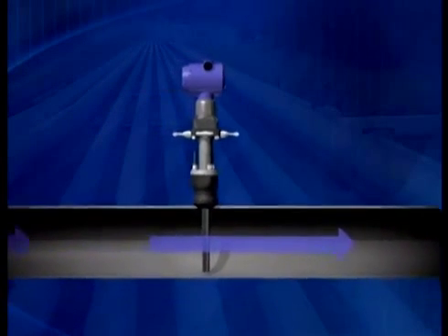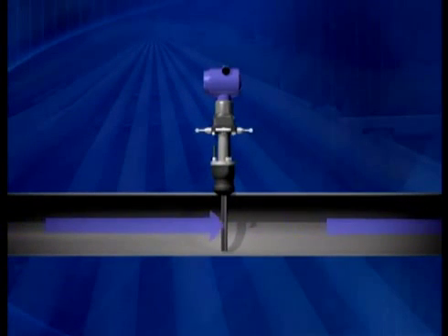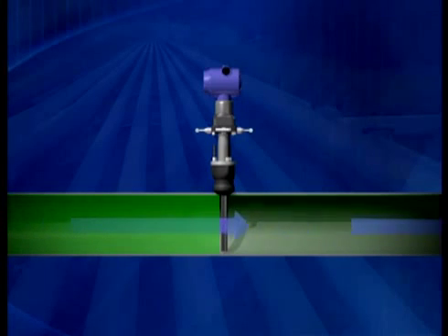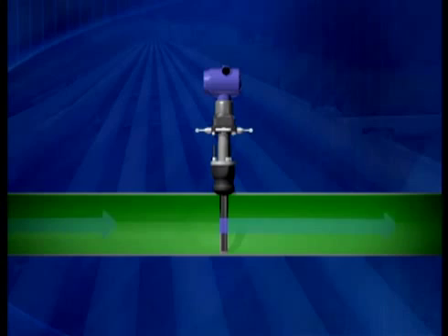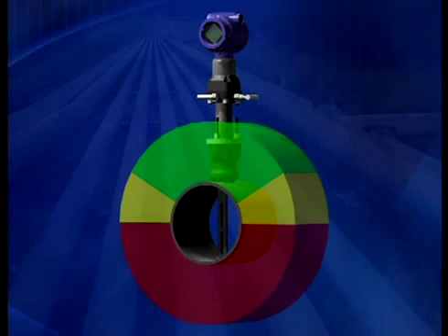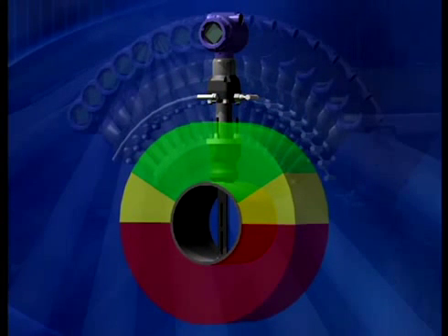Considerations in reviewing the location chosen for installation. First, there must be sufficient straight run both upstream and downstream of the mounting location. Second, the flow meter must be correctly oriented on the pipe for the application.